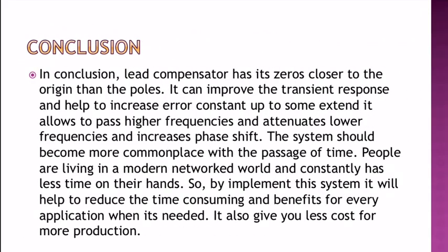In conclusion, a lead compensator has its zero closer to the origin than its pole. It can improve the transient response and help to increase the error constant up to some extent. It allows higher frequencies to pass, attenuates lower frequencies, and increases phase shift.